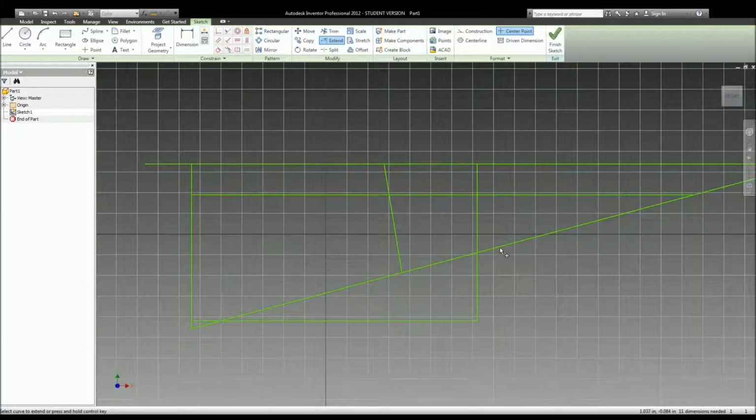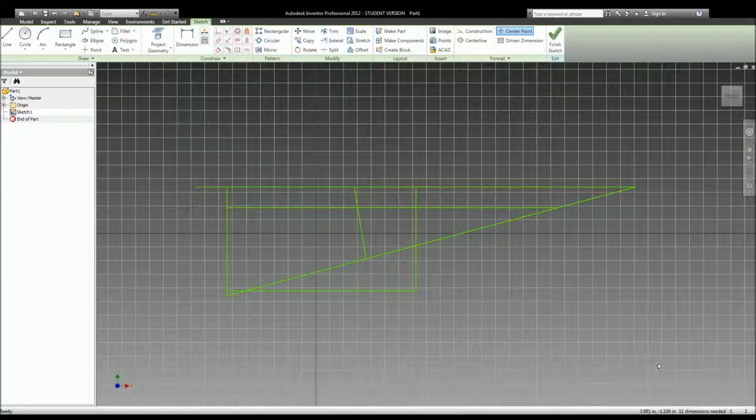So the extend, all it does is it's trying to connect two lines to create some form of a shape or a corner or something like that. It's very useful if you're trying to figure out if your lines line up at all. So say you have one measurement on one side of a project that you're doing, and you have a measurement on another side, but you can't tell that they are the same length or not, even though it says that they're the same length when you dimension them. So you can go ahead and do extend and see if the lines connect at some point. And if they do, then typically that means they should be on the same level, aka like the same height or something like that.